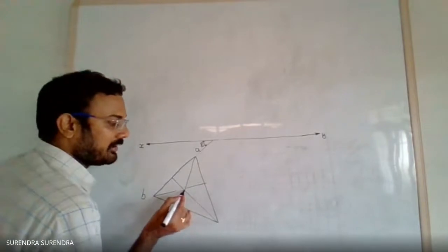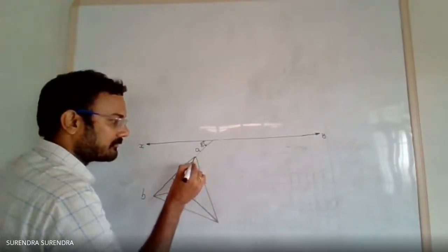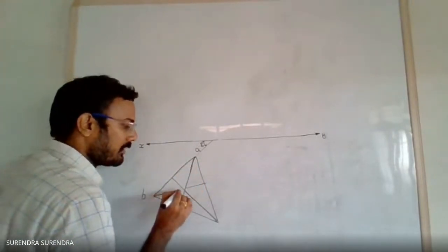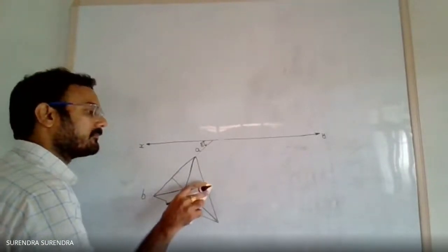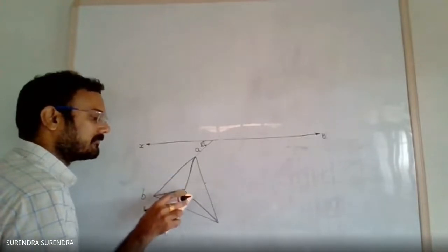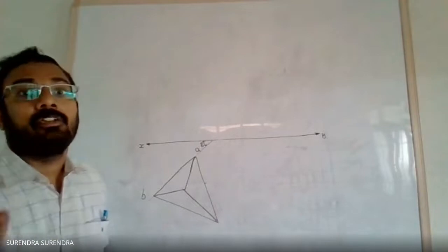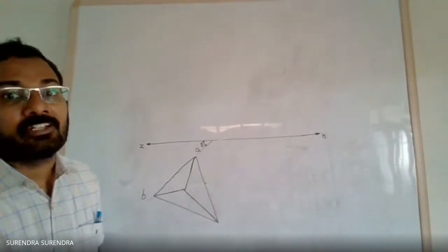So highlight only corner to the midpoint. Leave the remaining line with true edge, because this is only an imaginary line. This is the top view of a tetrahedron. Top view of a tetrahedron.